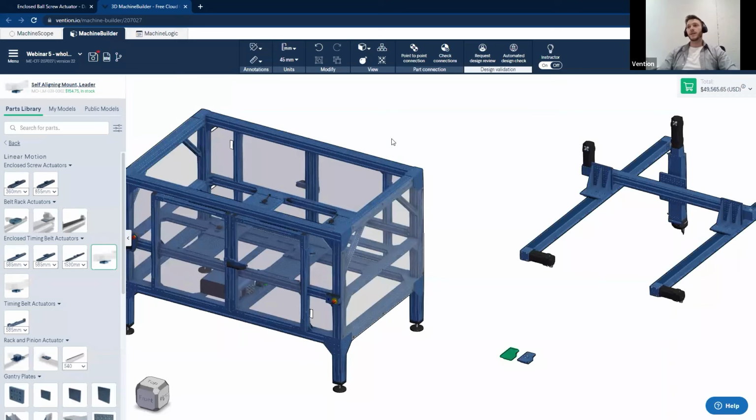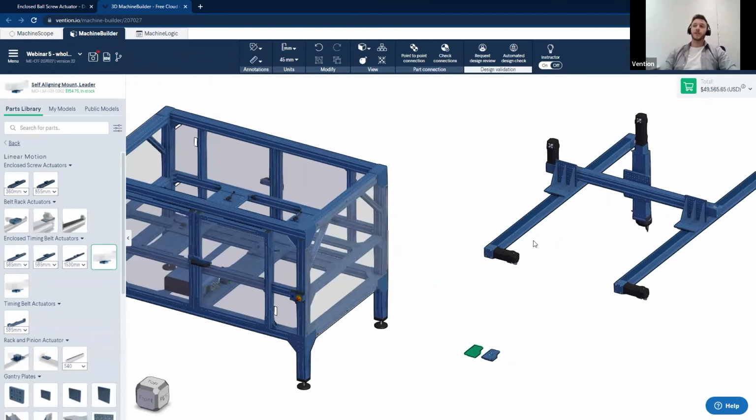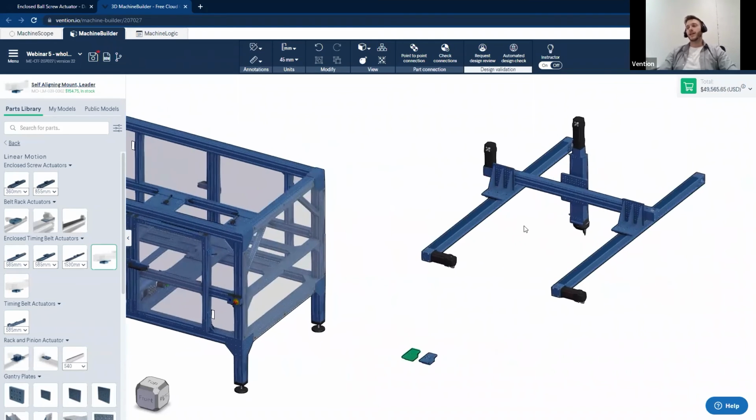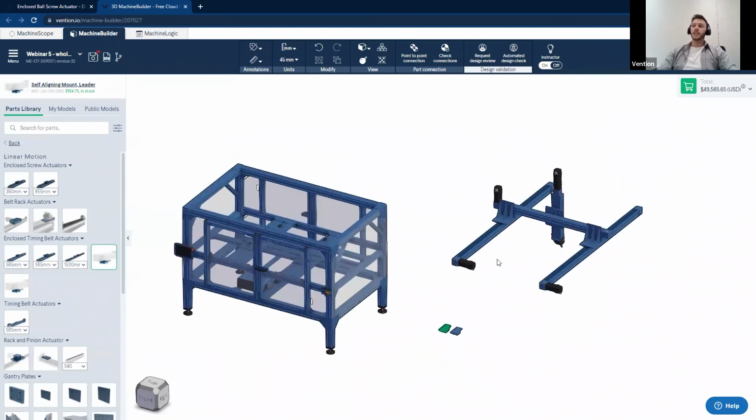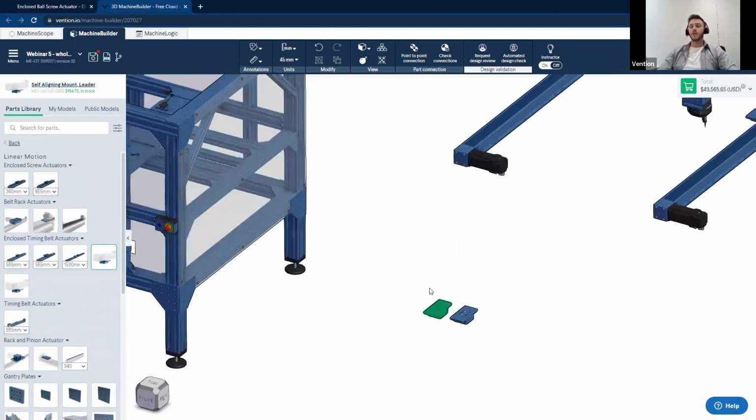The way they should be mounted is that you should have a spacing of no more than 1 meter between each plate. So in this case, if we have an actuator of 2,295 millimeters in length, we'll have 1 plate at either end and 1 in the middle as well to properly support the load. With that, it will be fully supported. And once actually attached to your structure, the system is fully constrained. You are not able to wobble or move it if you push it with your hand. It's really only during operation that they accommodate for those slight misalignments.